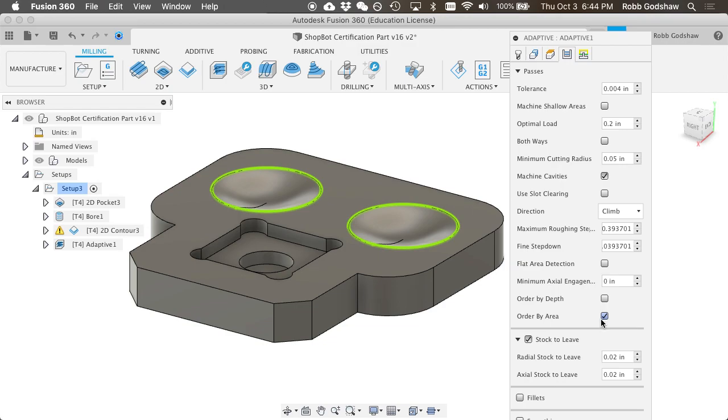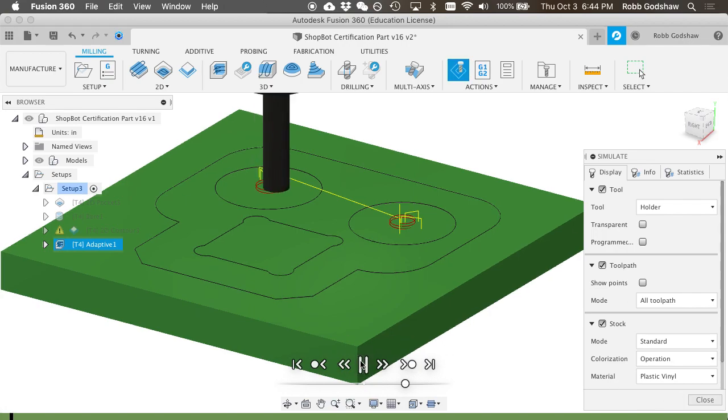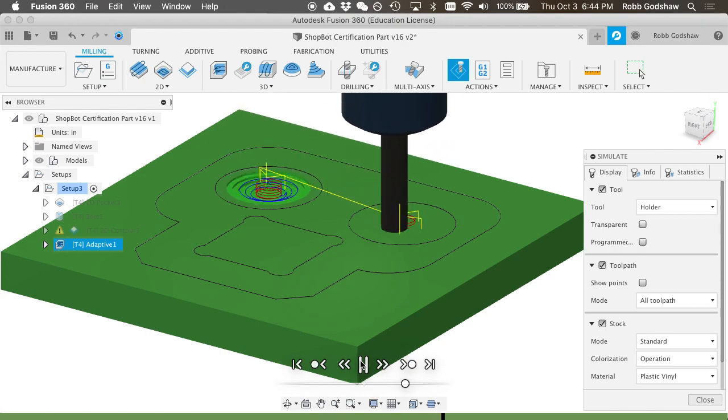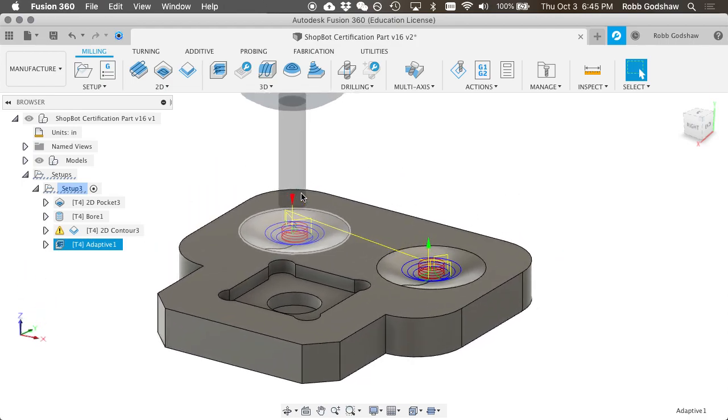That's exactly what we're looking for. Now if I push enter, it only makes one pass. Thank you. Good eye. So it goes in with a spiral, and then goes over and does that again. And this is just removing enough material that when we switch to the next tool, that tool won't be overburdened. And usually roughing is done with a square end mill because they can cut faster, and finishing is done with a round end mill.